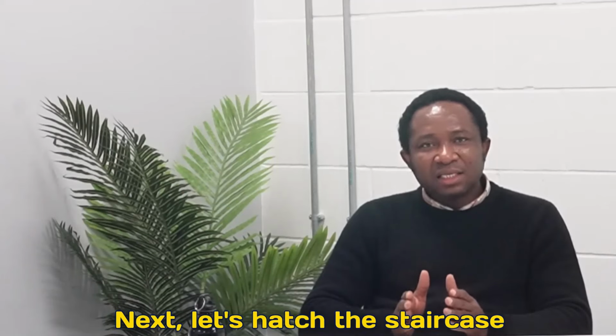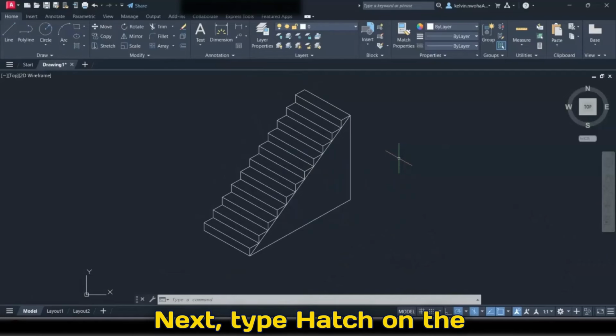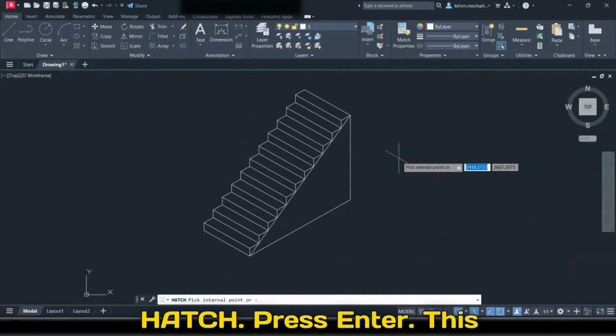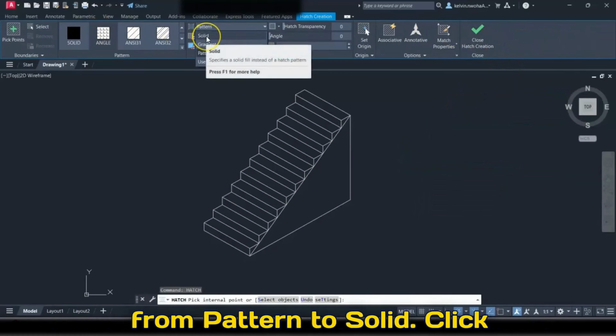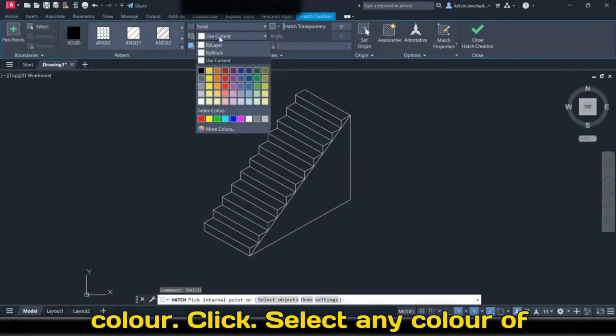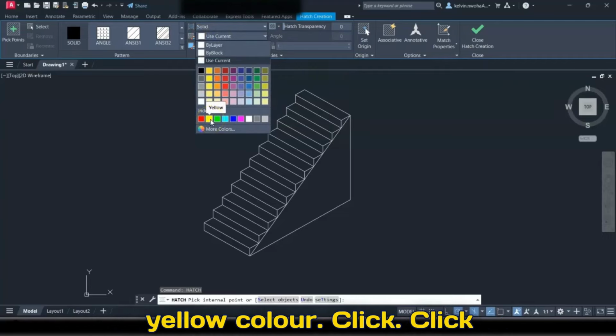Next, let's hatch the staircase with a suitable color. Next, type hatch on the keyboard. H-A-T-C-H. Press enter. This menu will change. Click here. Change this from pattern to solid. Click solid. Next, this hatch color. Click. Select any color of your choice. Let me use this yellow color.